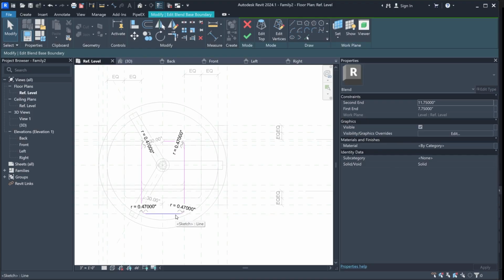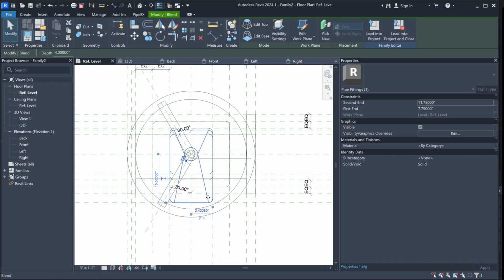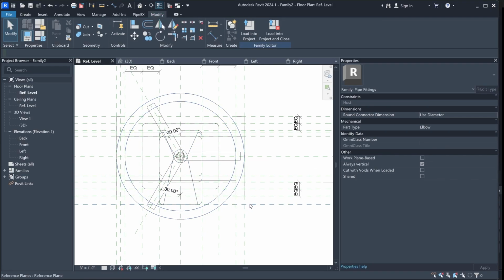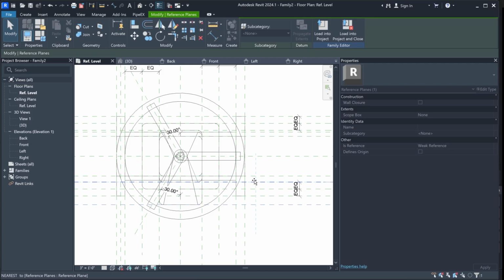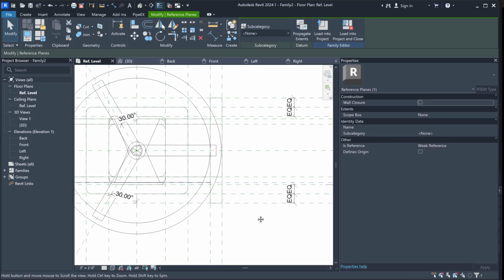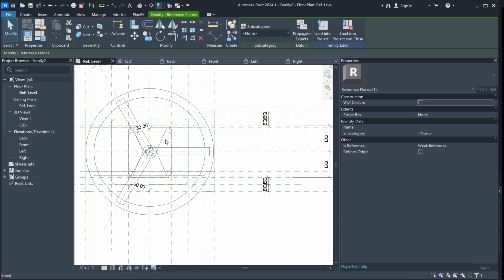No, we closed the padlock, but we forgot to add a dimension to this reference plane. So what we can do now is I will cancel, and oh, it's somewhere between these two profiles of the swept blend. Is somewhere here, and of course we cannot just leave it like that. We need to add a dimension. I will make them equal.